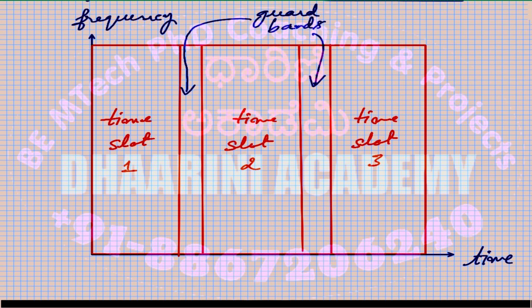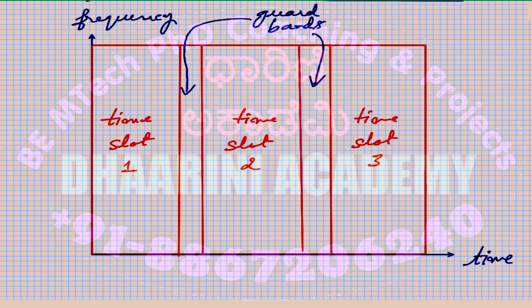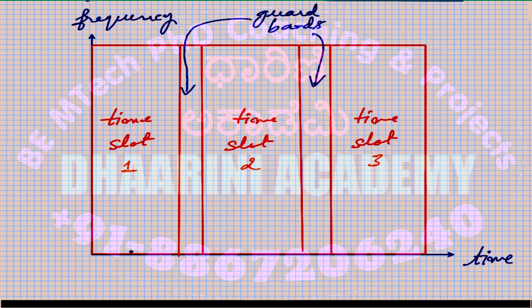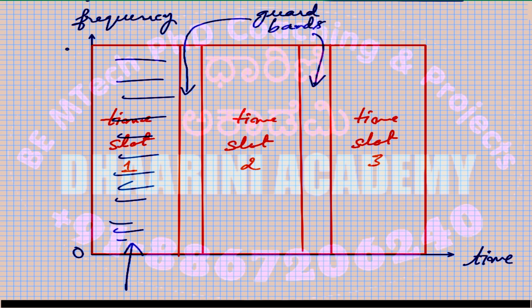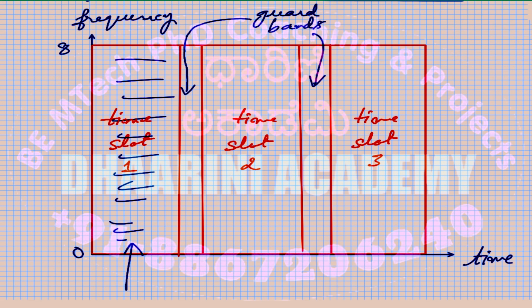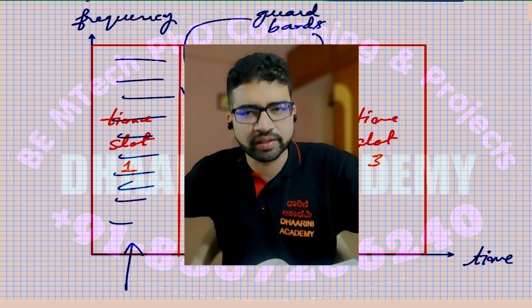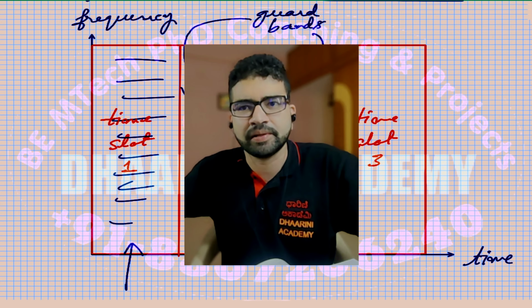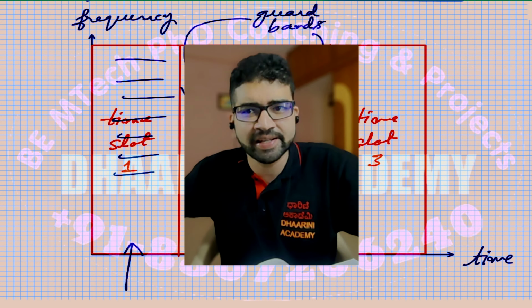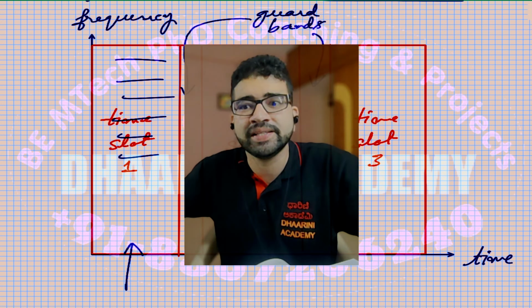So time is getting divided. That's our first observation. User 1 can send the message during this time at any possible frequency, starting from 0 to maybe the highest one, 8 megahertz, I guess, previously used. Within this 0 to 8, you can use any modulation technique you want. Any frequency, anything, but there is a restriction in terms of time. If the allocated time is 2 milliseconds, you have to stop within 2 milliseconds.